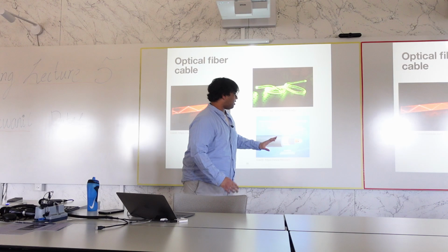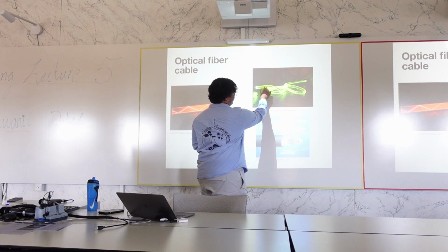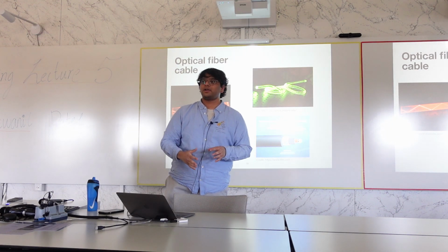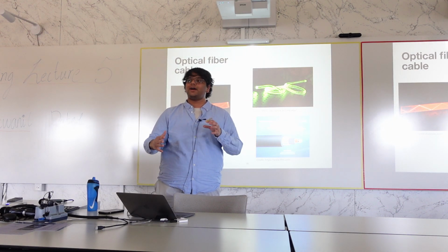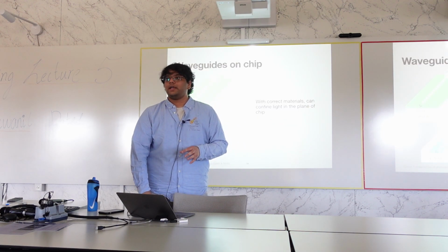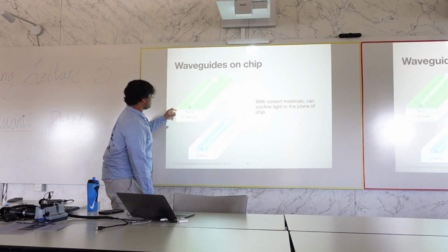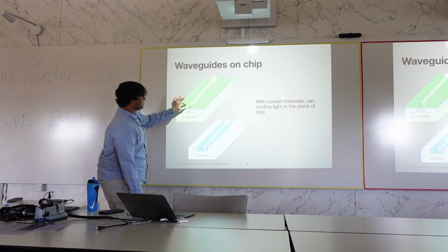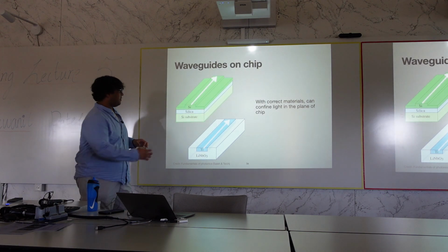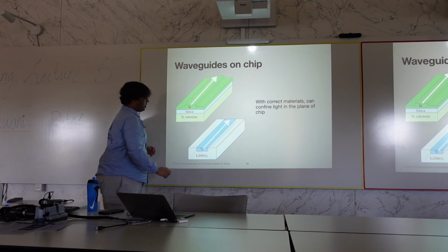So the only thing really important to us is to make sure that the core, which is the material itself, and the surrounding has the correct refractive index, or they're correctly aligned to make sure that we have the total internal reflection. And there are many flavors of this. You can have something like this where because the silica and non-silica has a really different refractive index, it makes sure that the light stays in this really small slab.